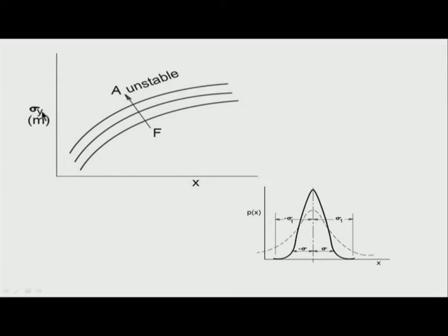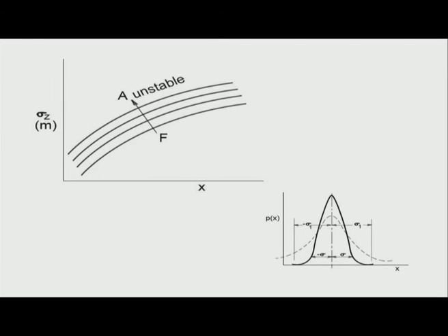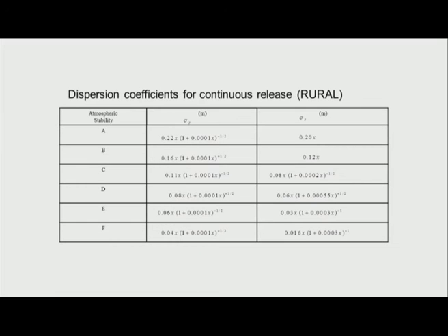And these are all measured for different conditions of the atmosphere: stable atmosphere, unstable atmosphere, different degrees of unstable and stable atmospheres. So also sigma z is measured. I did this on the board, and again you have the value of sigma z changing with respect to the direction along which the steady release propagates.